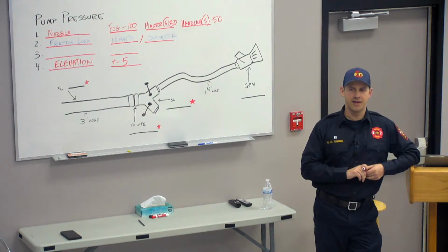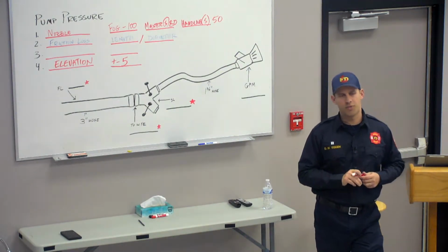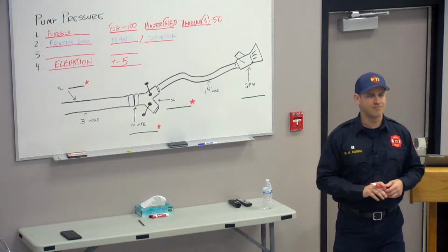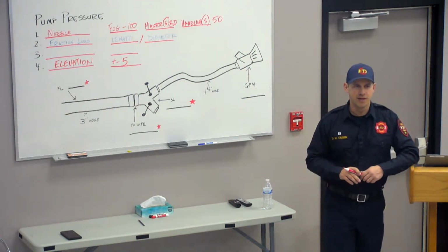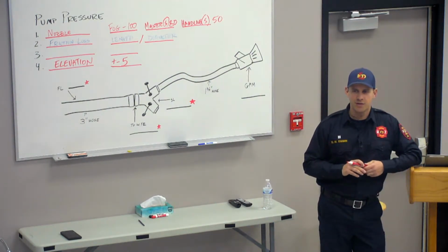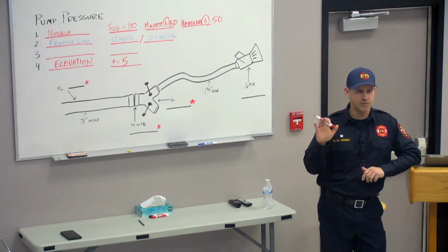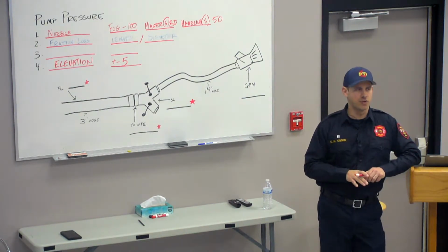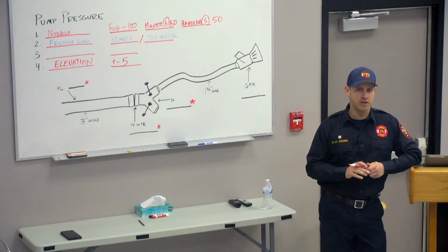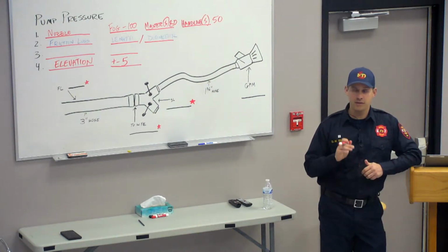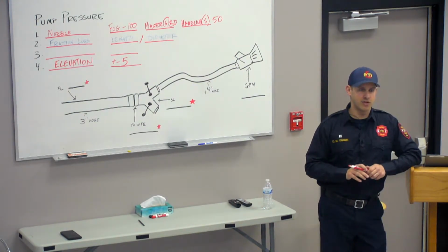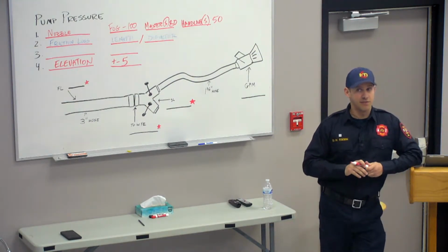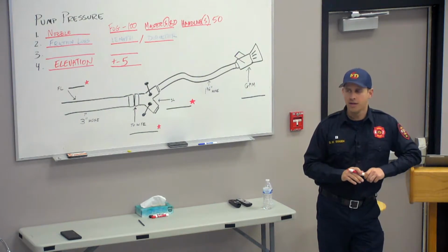So like we get into that 4th district area and we got all the parks, right? You pull up to one specific house in that Cherokee Park area, you might have a hill that is the equivalent of a 3-story building, right? We have to consider fighting that gravity and getting that pressure that we want up there. So we would probably add 5, 10, 15 in that scenario, right?